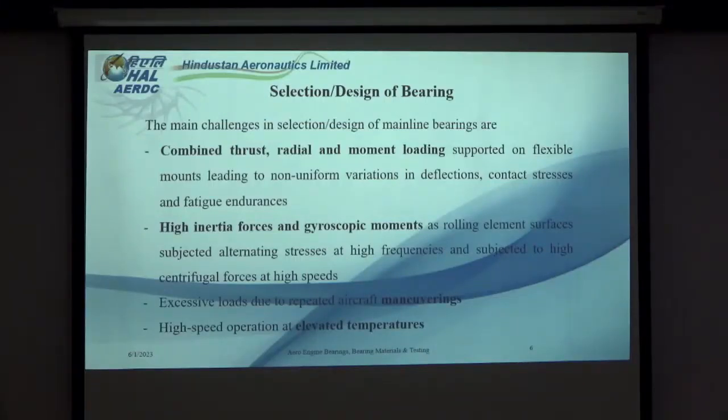The rolling elements have to undergo high inertia forces as well as gyroscopic moments, as rolling element surfaces are subjected to alternating stresses at a high frequency as well as high centrifugal forces at high speeds. Also, most aero gas turbine engines undergo a high level of maneuvering, so additional load also comes on the bearing. And they have to operate at high speed at elevated temperatures.